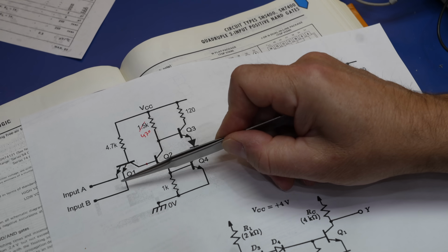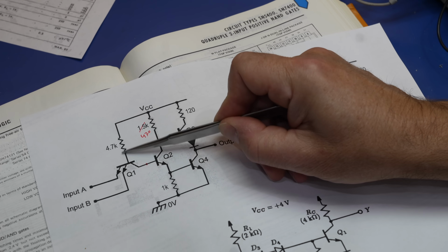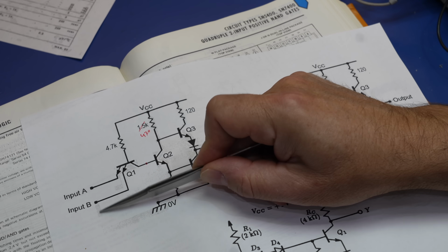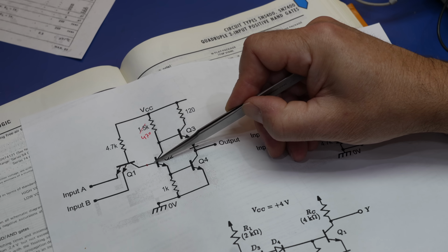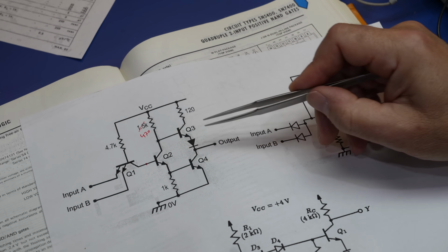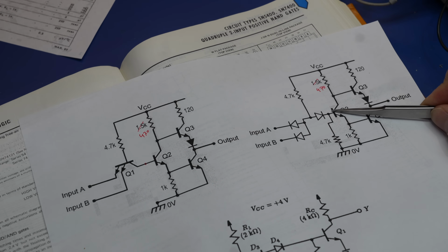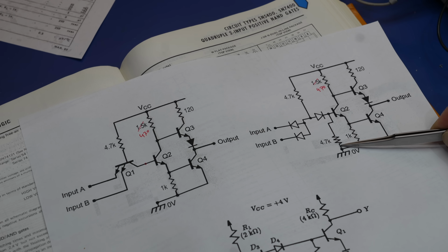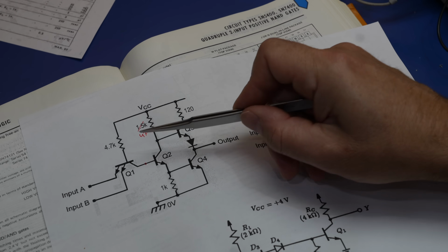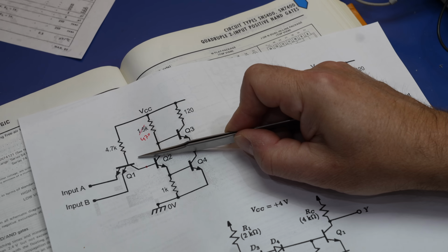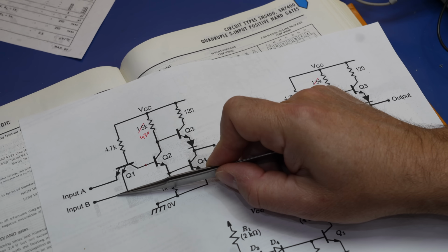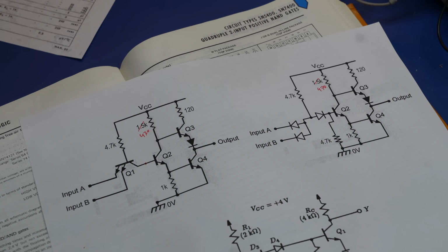As soon as there's a tiny bit of current that goes through input B, it will suck all of the carriers out of Q2 and drive it out of saturation very fast, which is absolutely not happening in the DTL case where it has to go through the resistor. So this thing is used as a diode and as a transistor at the same time. That's what makes it so good.